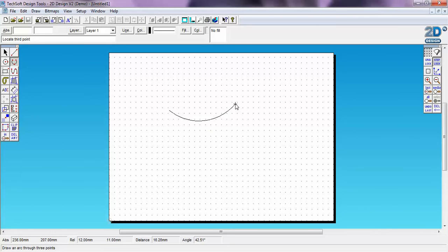However, this then allows you to change the curve and see how big and how deep you want it. Now remember, the length of the line will affect how deep the curve is, so if you want a slight curve, make sure to draw a long line, and you can always delete the excess length later on.